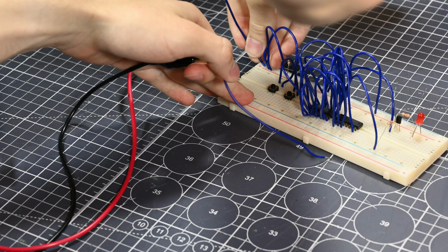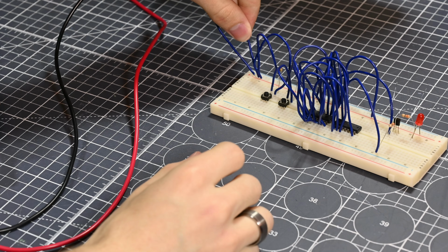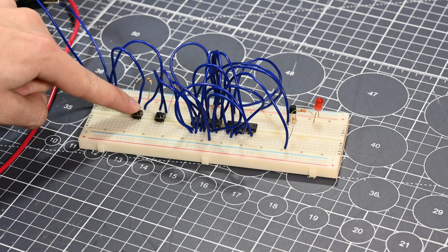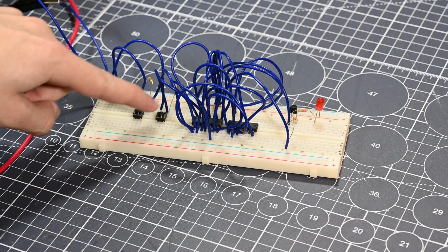And one good example of the NAND gate combinations going even further than just the regular logic operations is this circuit that I have built up using a total of 5 NAND gates. This right here is a data latch, which has 2 inputs, a data input and a store input, and of course it has one output.